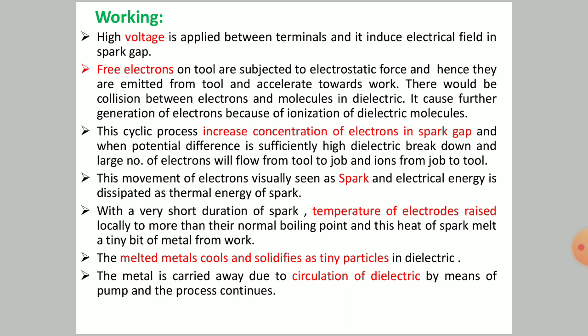And after the fuse, if we observe the particular location, we will see the wire is burned completely. They are almost instantly melted and solidified quickly. That terminology is nothing but spark erosion. That principle is utilized in electrodischarge machining. Let us look into the working principle.